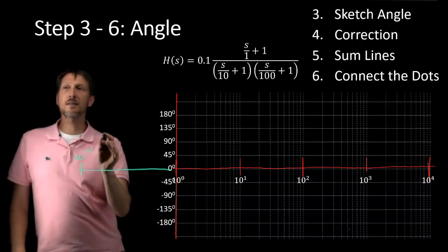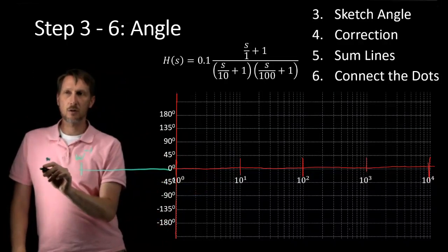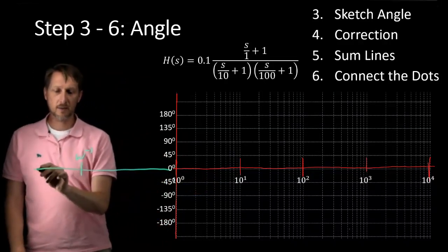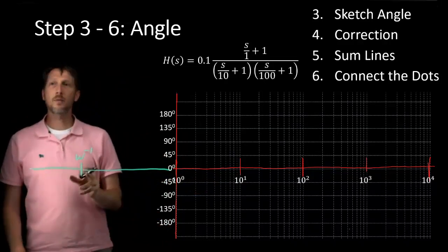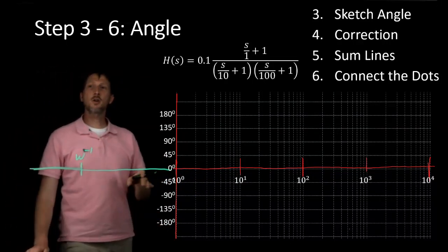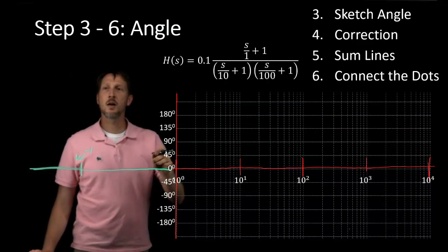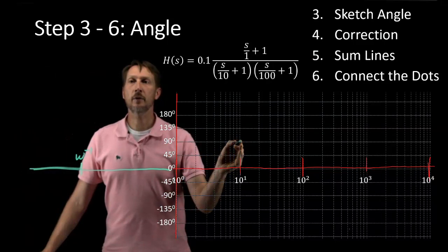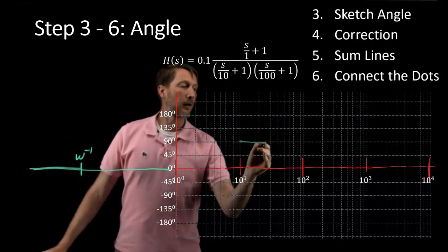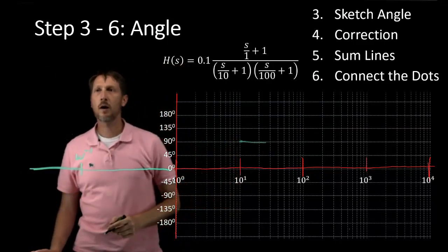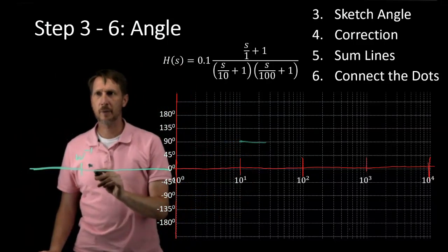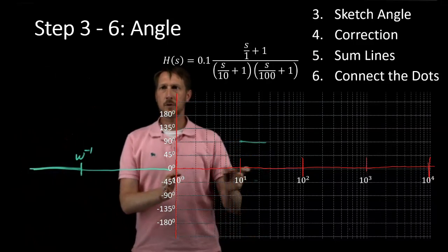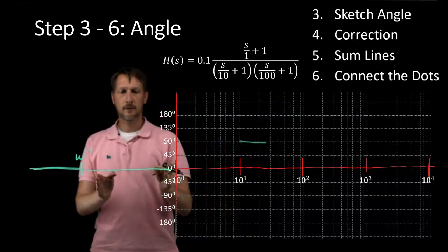And it said that we need to have an asymptote at 0 degrees. So it's going to have the asymptote along at 0. Then we're going to transition up to 90 degrees at 1 decade above. So that puts our data point right here, and that's going to be where our phase is going to go from and to. So let me see, we've got about that much for a decade.